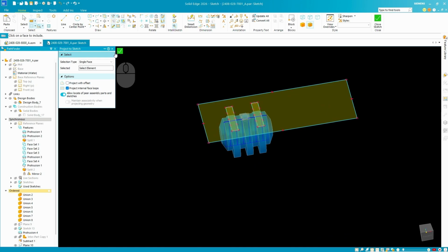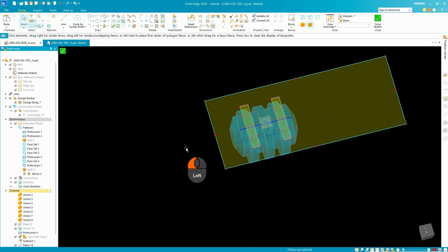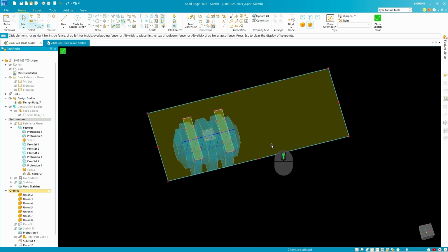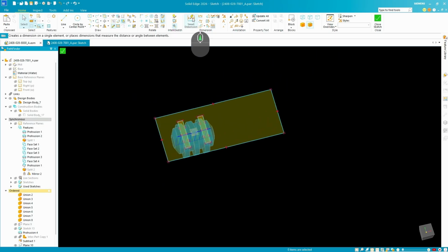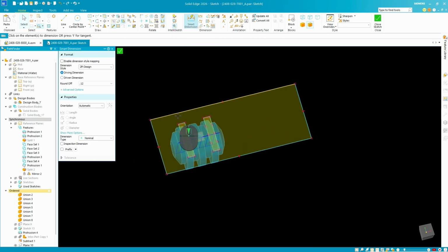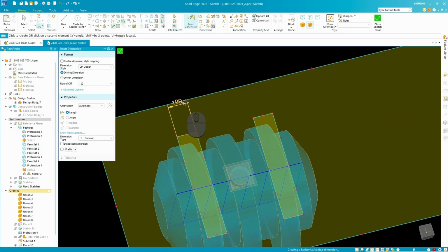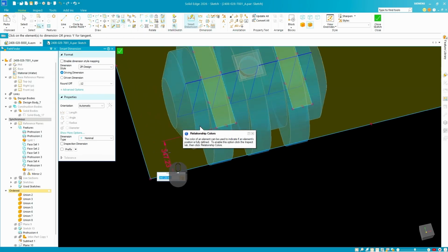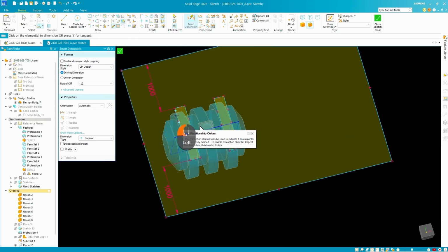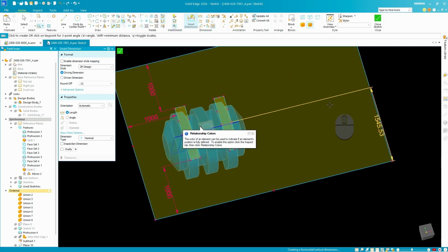So there we've done that now. I'm going to close project to sketch, and now we just want to constrain this rectangle so that it's always bigger than our tank. So just put a couple of dimensions on that, and we don't really care too much about how much bigger, just as long as it's bigger. So I'm going to make that 1000 millimeters and another 1000 millimeters, and I'm not sure here. I hope 1000 is enough. It is, and we go 1000.